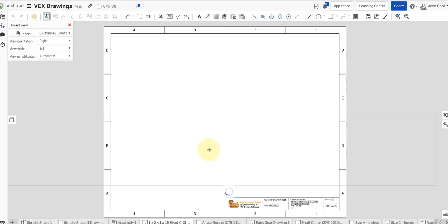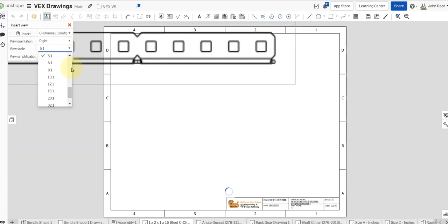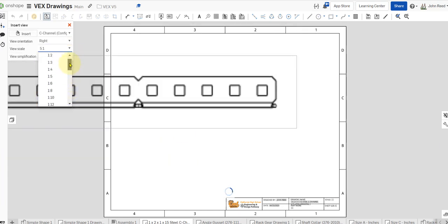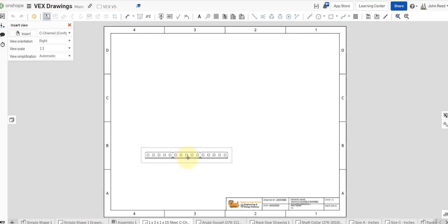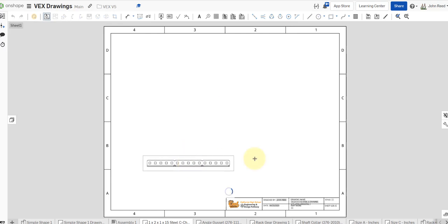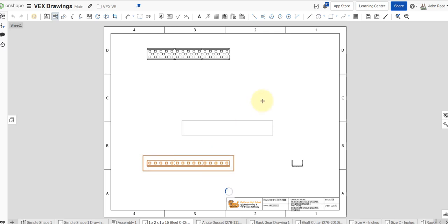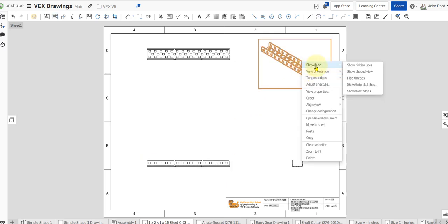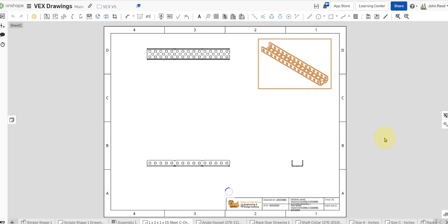And you can see it's enormous because Onshape thought we were going to place that other orientation. Let's just do that one. So we have that one, and then we have this one. We've got a lot of real estate here in the size C. Let's go ahead and just put all 4 standard views. And we'll come over here. And as usual, let's show this one shaded.